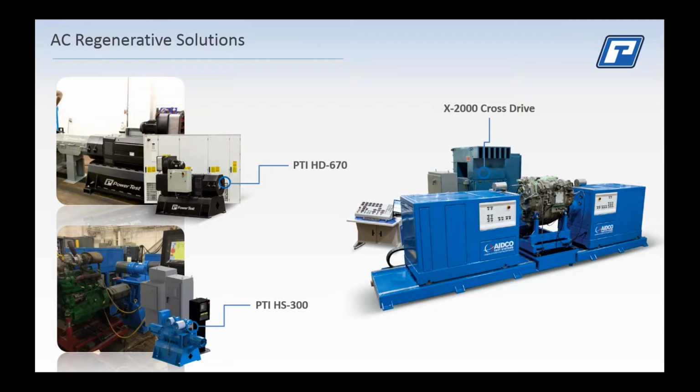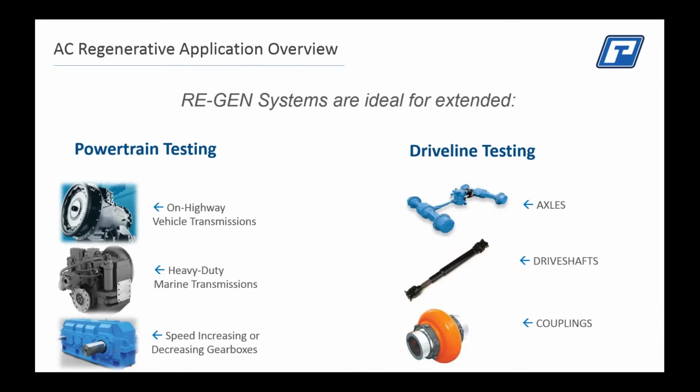We do a lot of different kinds of engine dynamometers in AC machines. The lower left-hand side shows a dual-ended 300 horsepower high-speed machine. This was designed to test a very wide range of engines, limited to 300 horsepower, but capable to 12,000 RPM. So it was designed to test everything from a UAV, a high-speed engine, through a small diesel.